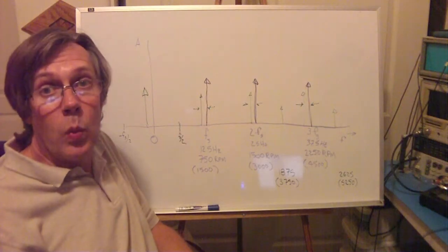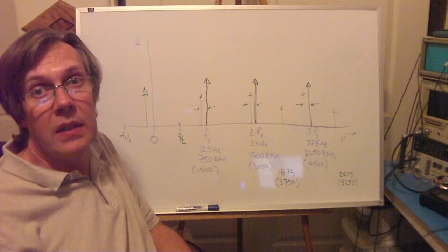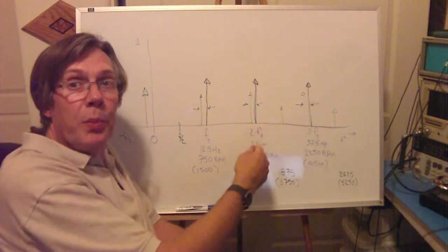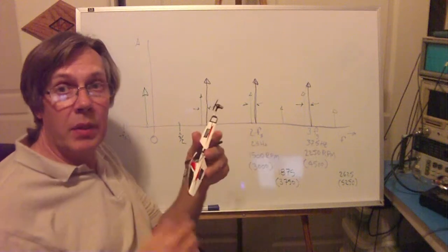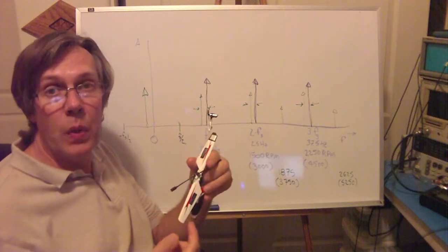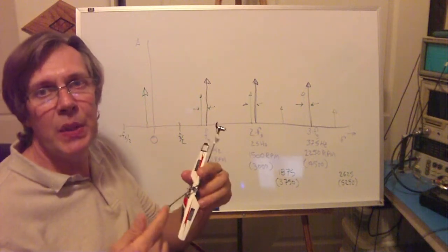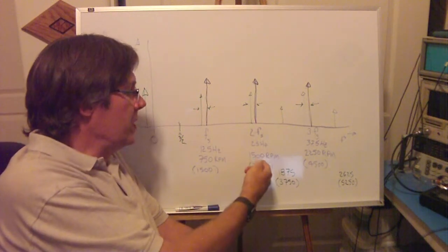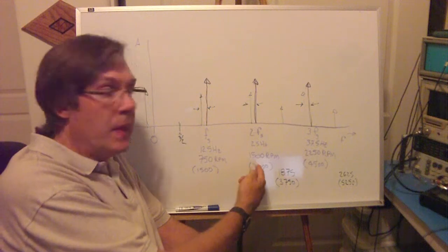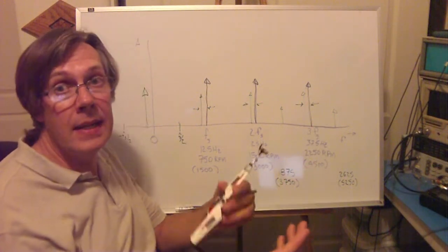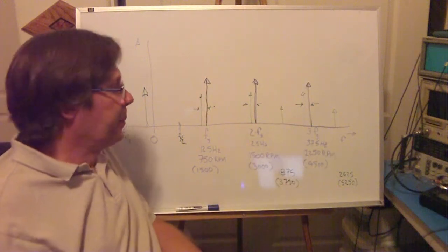So our demonstration went pretty much exactly as we predicted it to, in that for integer multiples of our sample rate, it looked like the blade was still and we had a reflector on only one tip and not the other. So it was an exact integer number of rotations per sample. 2 rotations for this case where it was turning at 1500 RPM, 3 for this case when it was turning at 2250. Remember, our indicator indicates double the rate.